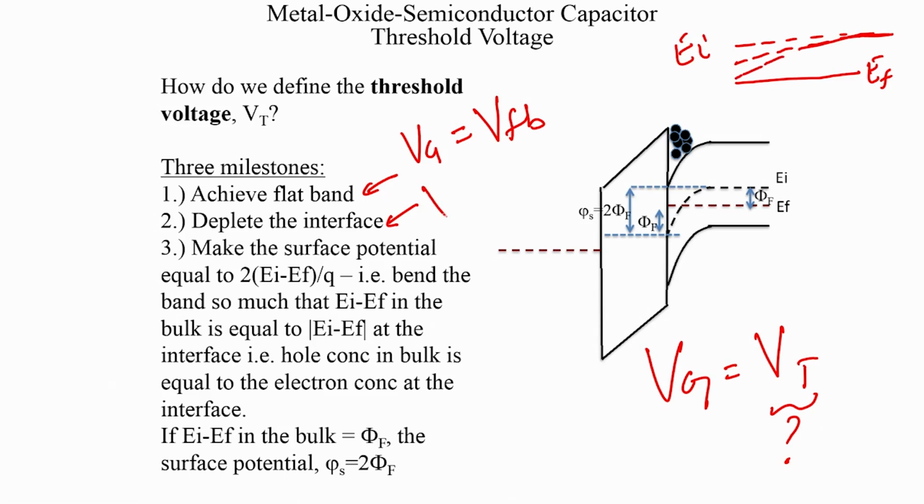So, you then have to cross the second hurdle, which is that you not only have added a flat band voltage, but you start depleting the semiconductor, and this total depletion charge divided by Cox, the insulator capacitance, is the effective voltage that you need to add.